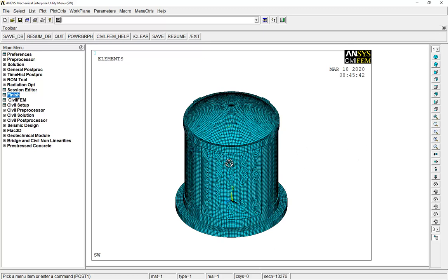So well, the first tool is generating the equivalent shell model. We can generate the equivalent shell model in just some parts of the model or in the whole of it. The way to do it is selecting just some parts of the model, for example the roof, the slab, different parts of the walls, and in that element selection we also select the nodes of one of the exterior faces.